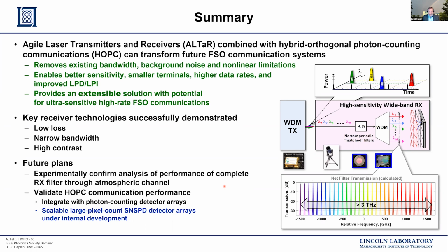For the transmitter side that I talked about, it's a directly modulated laser. Lasers have flown in space without any significant degradations in both operation in vacuum and in the radiation environment. So I'm not concerned about the transmitter side based on heritage designs that have successfully flown. The diffraction grating technologies that we're considering are also passive, etched in glass, and I don't envision any significant environmental concerns. But of course, the devil's in the details, and if we were envisioning flying these kind of designs, you better believe we would test them in the operational environment to make sure that there aren't any gotchas that we didn't anticipate.